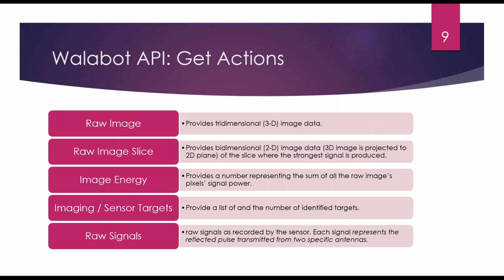Great. So let's say you've programmed your Walabot, you've configured your Walabot to do one of the three things. Let's say you're trying to see into walls. So you've chosen the imaging profile and you've chosen a specific arena for it to look at in the wall. And then you've chosen, let's say, a threshold, because the wall is not exactly a uniform wall, so you want a higher threshold. Then you use the start function, and you start recording and see what you get.